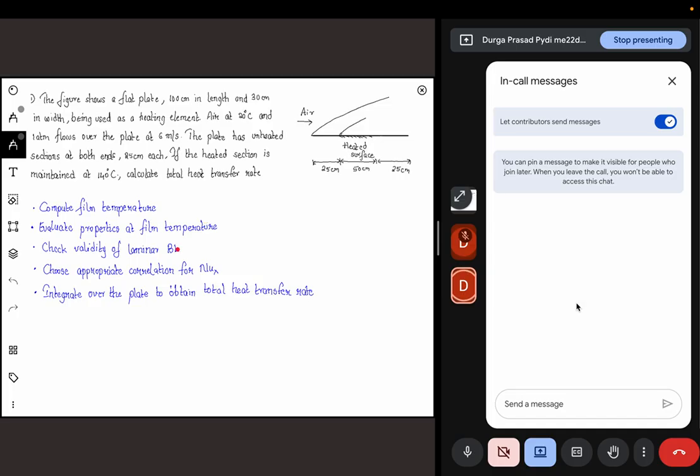If you are in the laminar regime, then you have to decide which correlation to use for Nusselt number. It is a constant temperature case, but there are still other cases even within it. If delta T by delta is less than 1, we have one correlation. If it is greater than 1, then we cannot use that particular correlation. We have to check whether that criterion is satisfied, and if it is, then we have the Nusselt number derived previously that you can use.